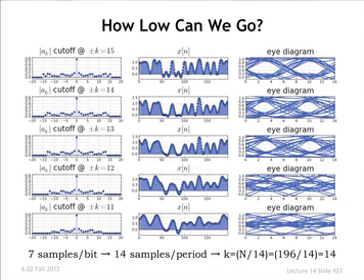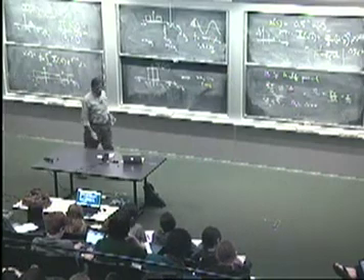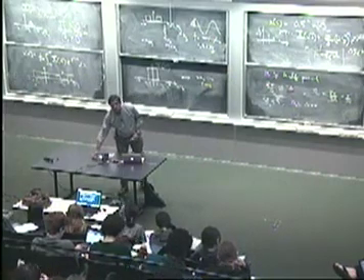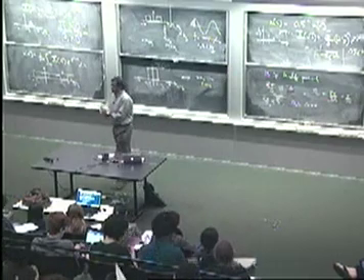And the corresponding eye diagrams that you construct, well, at a certain point, somewhere around here, you'd be a little nervous about trying to find a place to threshold and decide on what signal you have. So this is not a noise issue. This is a distortion issue. It's distortion induced by the channel, and it can all be understood in terms of what the channel is doing to the spectral content of the input. Okay, I think we'll continue next time to get more insight into this and start on the topic of modulation.